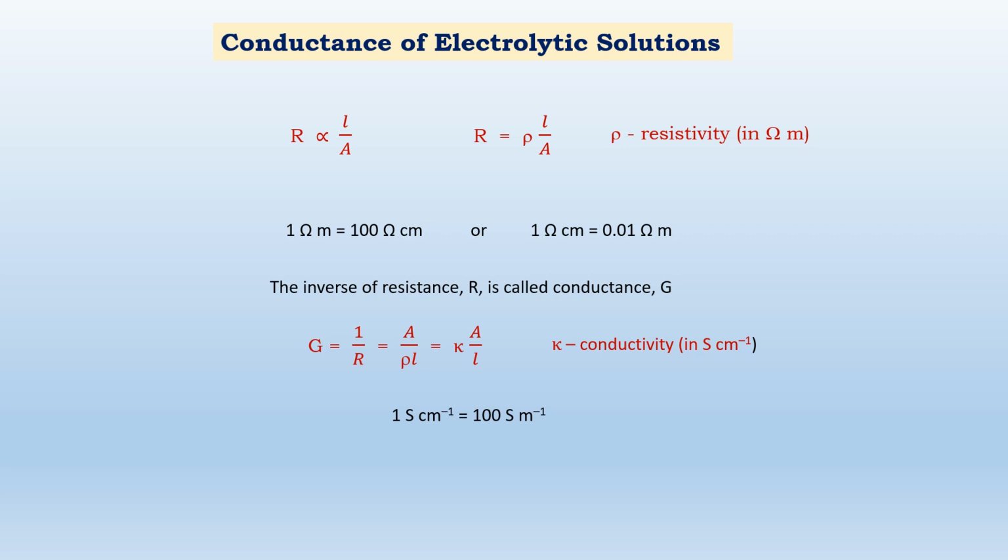Why? A thick wire has a lower resistance. A thick wire has a higher area, and hence it has a lower resistance, because area is inversely proportional in the formula. If they put a thin wire, it will have a higher resistance, and hence heat will be generated. It may even catch fire. Because of that, they will put the thick wire.